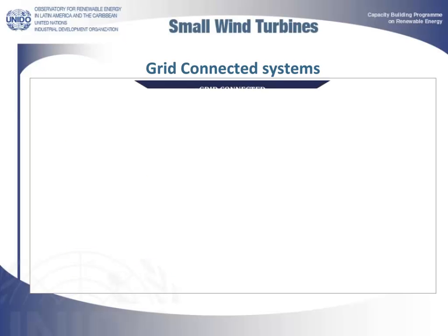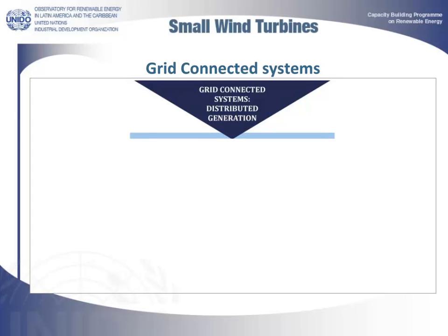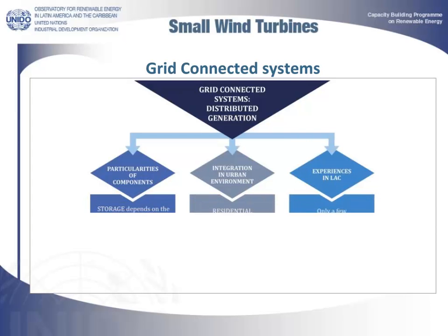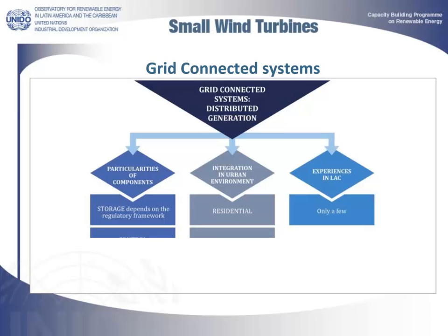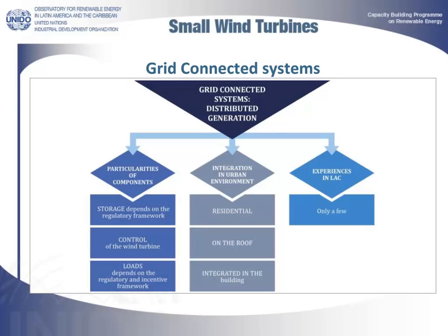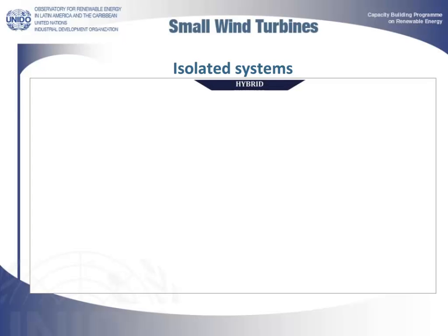One of the opportunities provided by this configuration is the elimination of long-term electrical energy storage systems, that is, batteries, by providing the grid with both power stability and storage capacity. Also, it is usual that the wind turbine controls themselves, that is, rectifier plus controller plus inverter, are sufficient for the proper functioning of the system, not requiring supervision. The application of small wind turbines connected to the grid in urban environments has great potential. Let us look at some peculiarities.